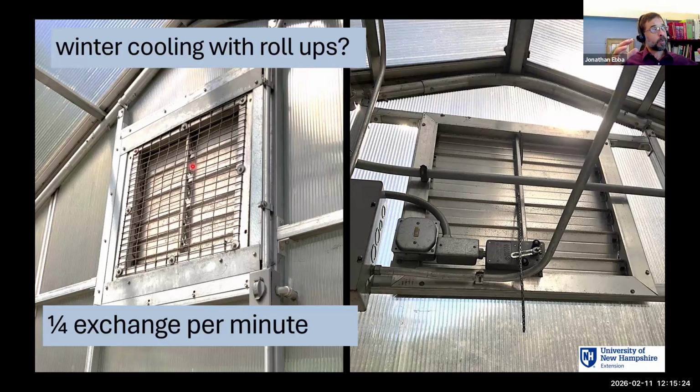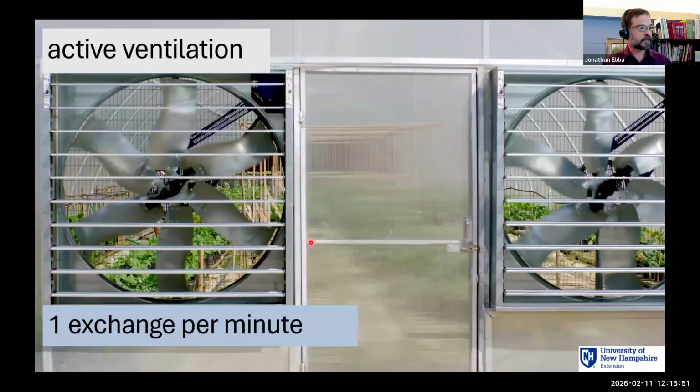When we're not in roll-up season, so in the wintertime, we can still get kind of hot in that house. And if we're growing in that house, it's nice to have a small fan. It can be sized much smaller than the summer exhaust fans, with an intake louver on the other side. We can put those up in the peak. And so I could imagine a house that had roll-up sides, this configuration, and does not need this configuration.